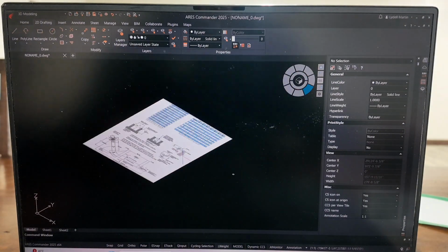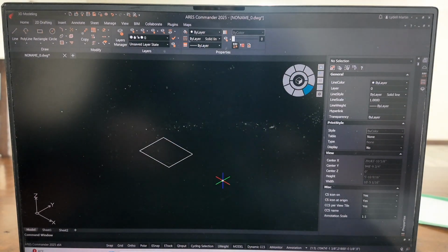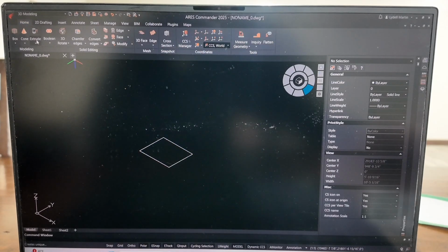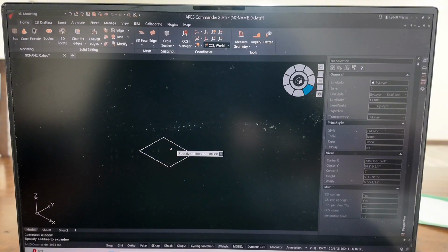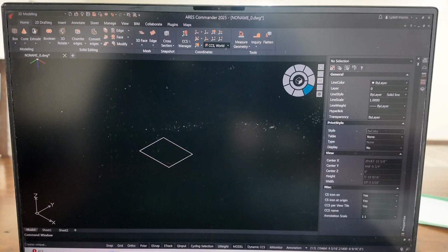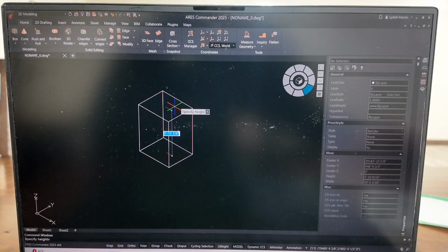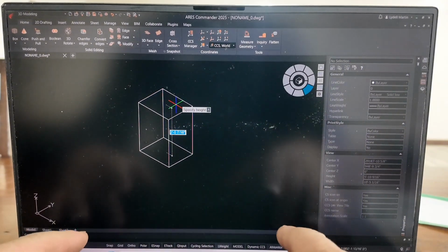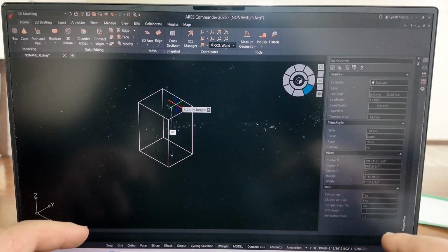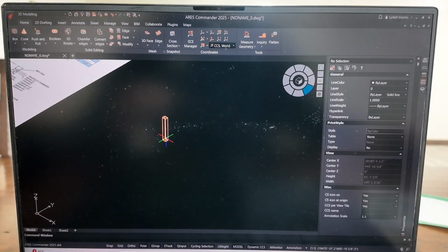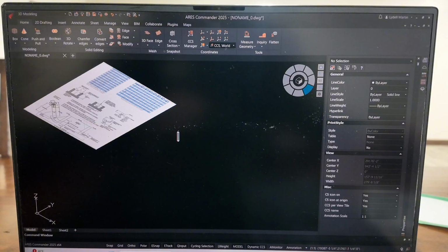I'm going to start out by making a 10-foot long piece of trunking. Up here in the top left, we're going to select Home, and we're going to select Extrude. No, we can't select Extrude. Where Extrude is, we hit the drop-down arrow, go down here and select Push-Pull. When we get inside this, it turns blue. We left-click, pull that up, and type in 10-foot. Enter. Made a 10-foot long piece of trunking.